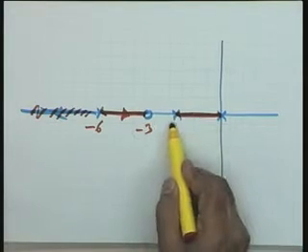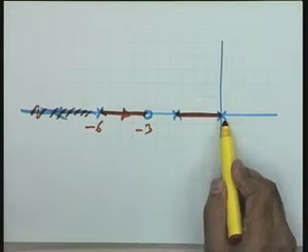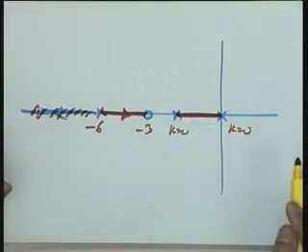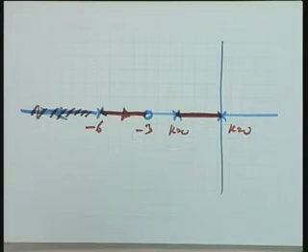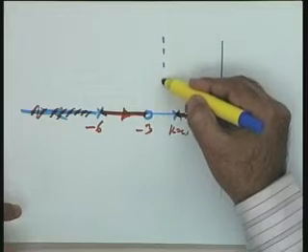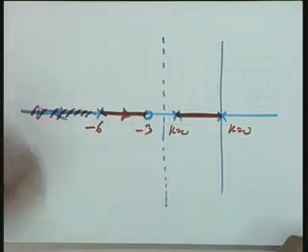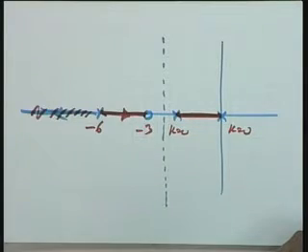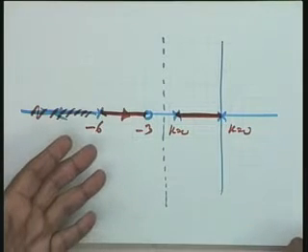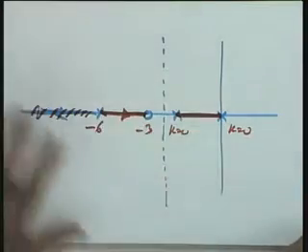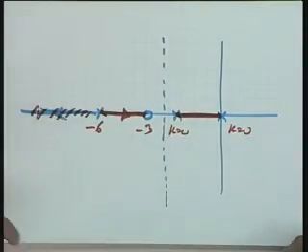Now these two branches, k equal to 0 here and k equal to 0 here, are the two starting points. What do you expect in this case? Well, it is very difficult to say because it has to go to infinity. Which way it goes to infinity depends. So naturally you require the asymptotic angles and the centroid. If I had given you this information, then you would have immediately given it. Otherwise it is very difficult to make a guess, because they have to go to infinity, but there are infinite directions for it to go, and therefore that guess is difficult.